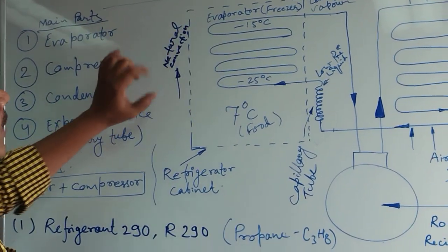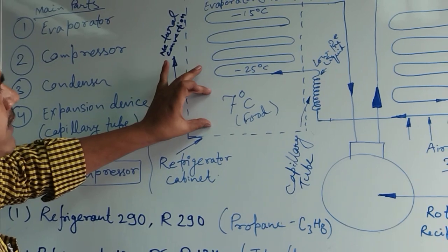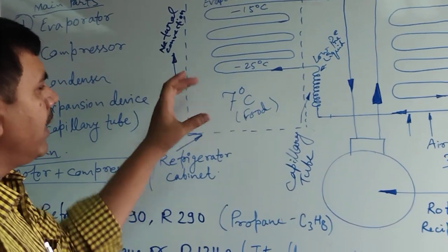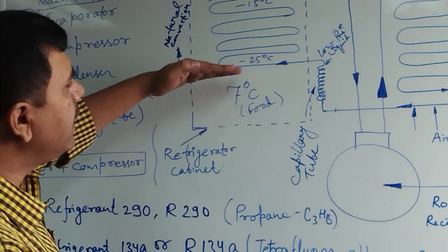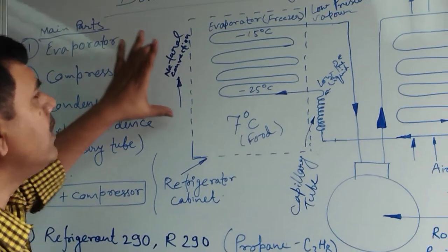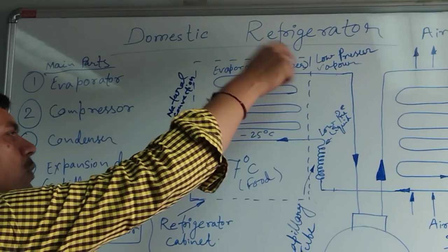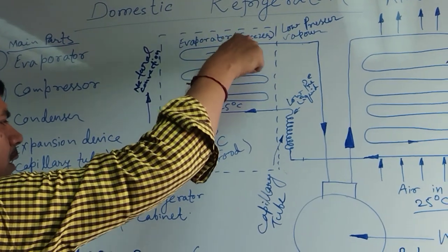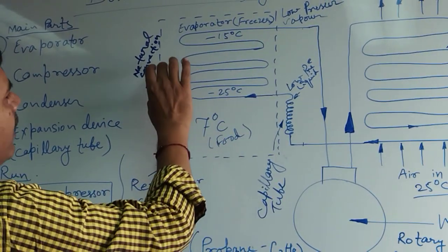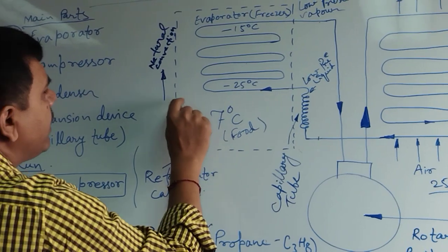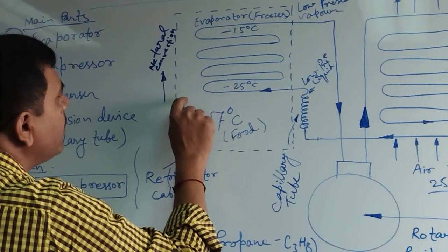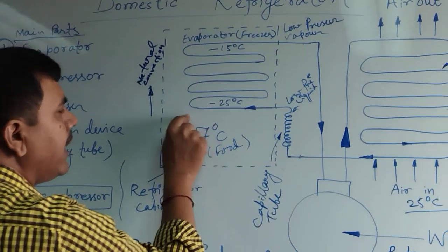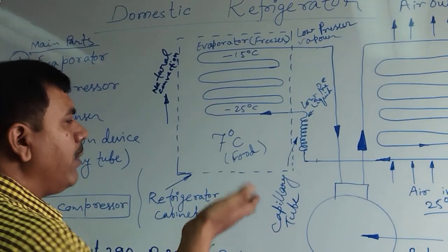Here, through natural convection, some heat is received from the cold chamber holding the food, and the temperature slowly goes up. The cool air slowly goes down through the evaporator. This is the evaporator unit, and just below it is the freezer unit, below the chiller tray and some compartments.